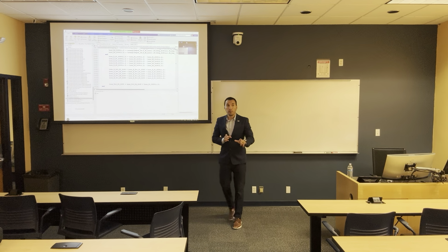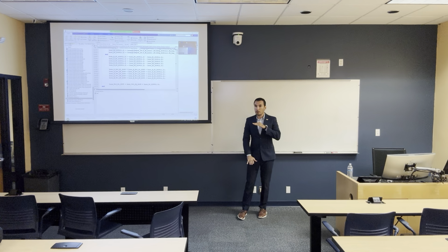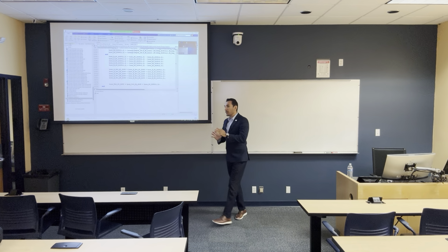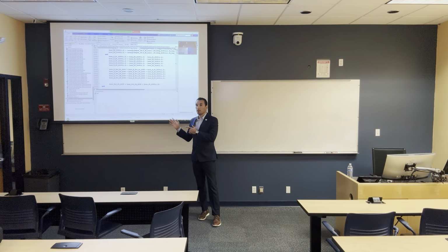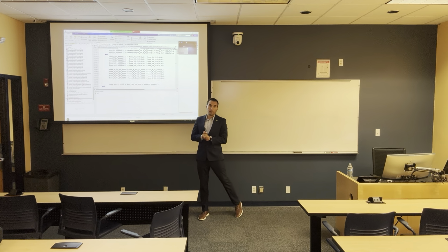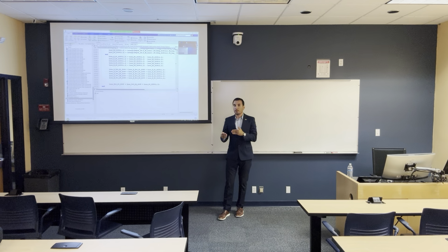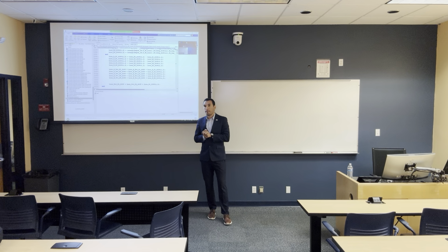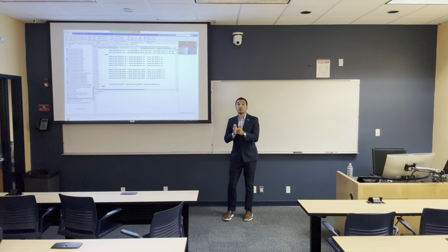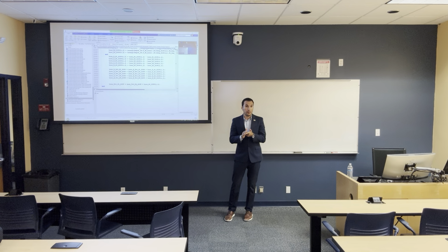So if you have a building that is elevated from the ground on the shoreline, and this is a kind of mitigation measure, what do you think is the best way to model this mitigation in our code? Or what is the difference? How is this going to be any different from other mitigations that we are doing? Adding more than the foundation height, which is the height of the first story. So close. So what is the foundation height going to do? First floor elevation. Exactly. So the first floor elevation is the only thing that is going to be different.